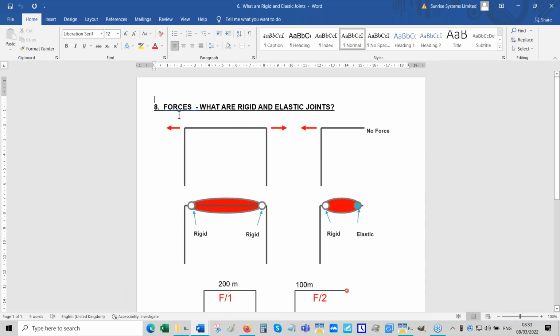See this one here, if you consider the unbalanced force along that pipe, it is the difference between the force there and the force here. So you would define them as rigid joints at both ends. But here, see, it's a freestanding pipe.